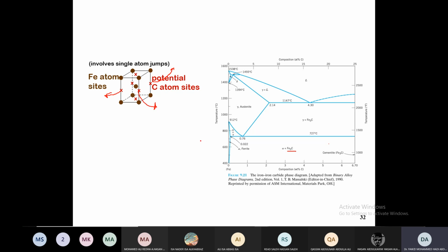If we go and temper at high temperature here, let's say comparing with high temperature or at low temperature, let's say this is 400, let's suppose we are below that. I don't want to go below. Let's say this is at 250 and that is at 600 degrees centigrade. Will there be any difference between the material produced in each case? And definitely there will be.